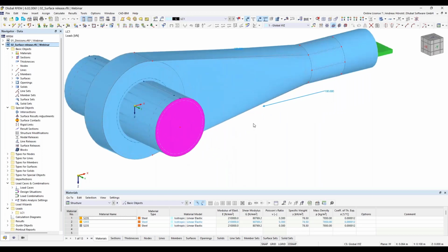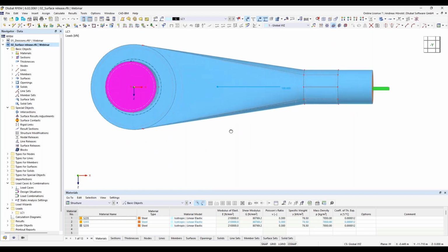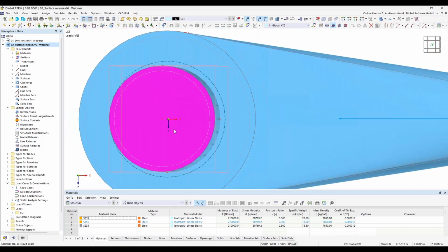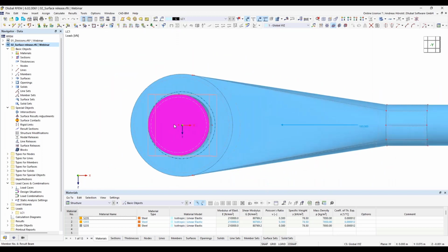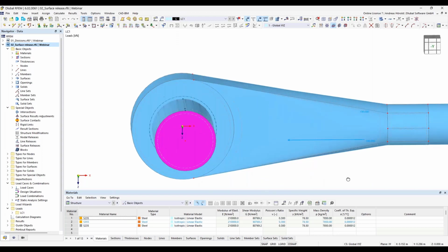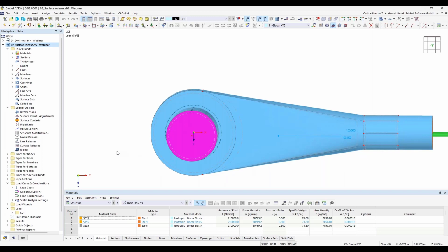This example shows a grommet, through which a bolt is put in that place. The contact conditions in this area should be defined so that the surfaces under tension can detach from each other. So if I load the bolt as we defined, it should be released on that edge here. So how to do that?